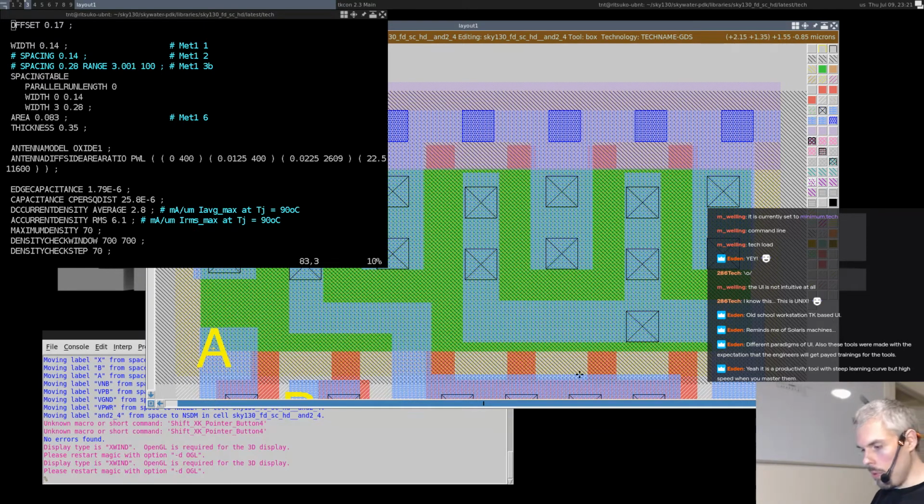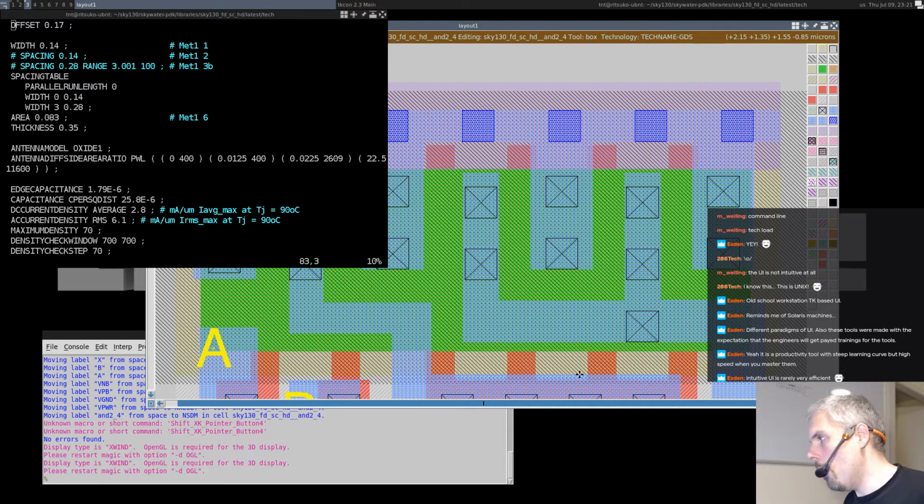So in the standard cell library, you find things like AND gates, flip flops, stuff like that, but you won't find, like in an FPGA where you have block RAM, stuff like that. You won't find that in the standard cell library. You need macros. Those can sometimes be provided by the fab themselves. In the classic model, you basically ask the fab and they give you an SRAM macro that describes the memory of the size you want, with the spec you want, within what's available to them.